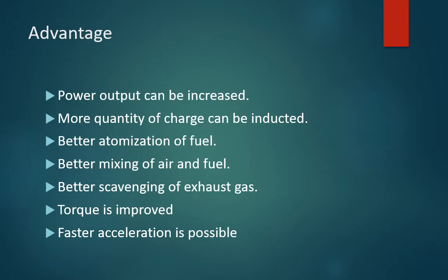Let us look at what benefits we get out of supercharging. What is the advantage of supercharging an engine? The following are the benefits we get. By increasing the pressure at which the air is taken into the cylinder, the density of air increases, and the pressure of the air also increases. If the density of air increases, we can immediately observe that for the same volume the mass of air would have increased, if the amount of air we have taken into the cylinder is more than the previous volumetric efficiency. That means the volumetric efficiency would increase. That is one benefit of supercharging.